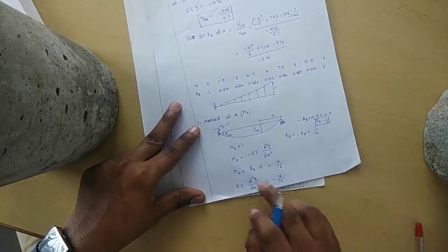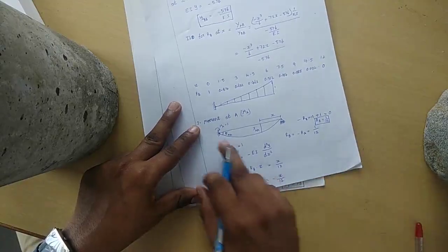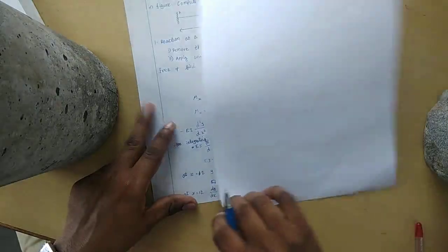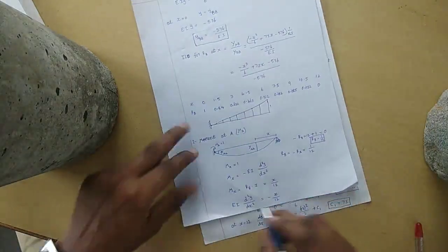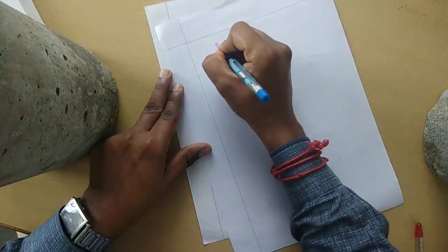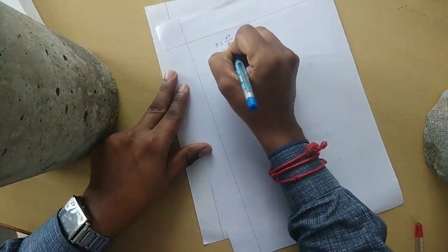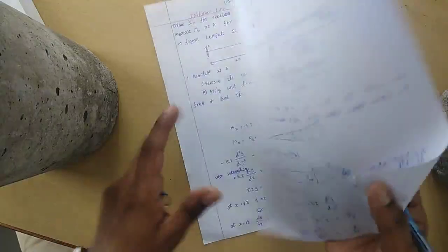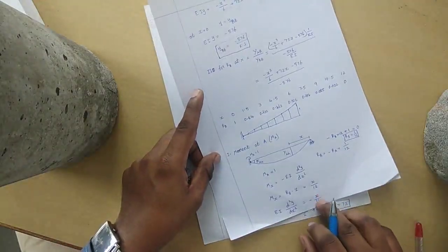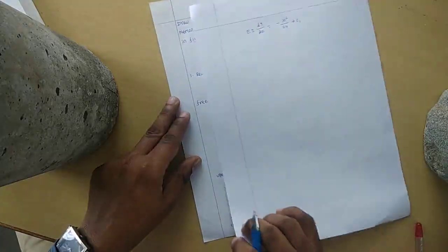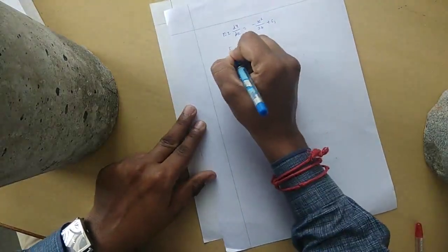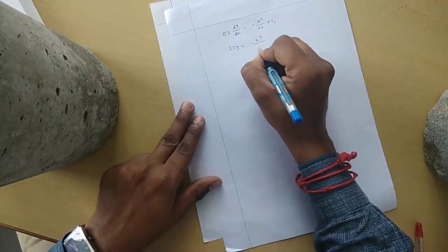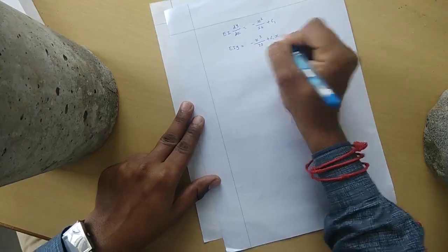Again we need to find out the displacement, because our ultimate goal is, by applying the unit moment or unit force, to calculate the deflection caused due to it. So I am going to integrate this equation. If I integrate this, then the value will be EI dy by dx equal to minus x square divided by 24 plus C1. I have integrated this, so x will become x square by 2. Already we have 12, so the value will be x square divided by 24. Next, upon integrating again, EIy equal to minus x cube divided by 72 plus C1x plus C2.